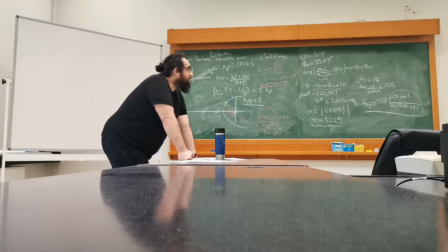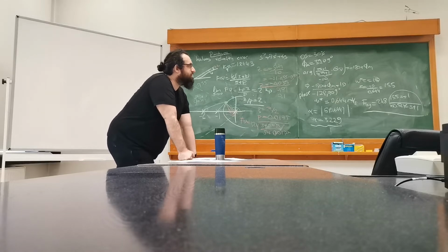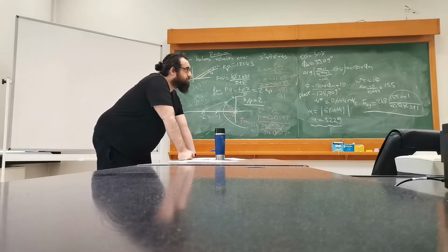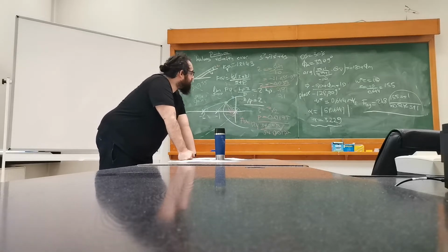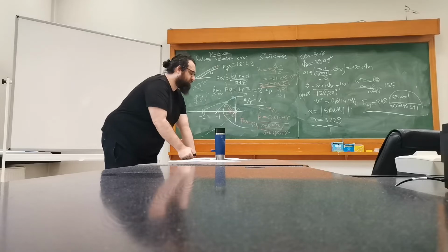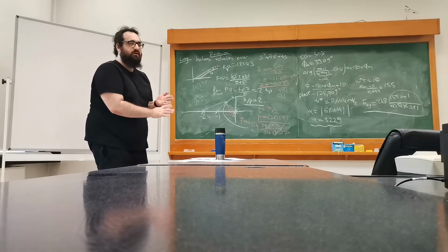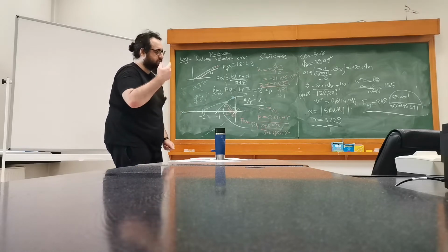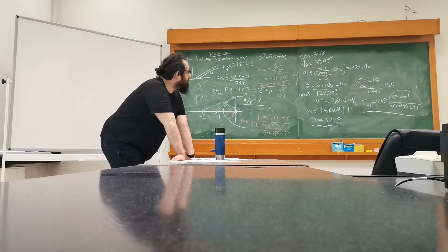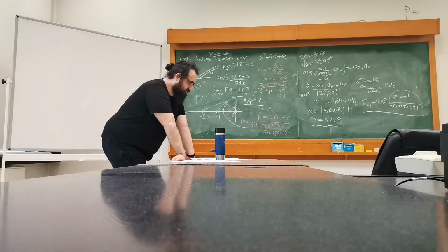So yeah. It seems like on the right we have a better way of choosing it, because we definitely find out what alpha should be, what tau should be. We just directly calculate that. But here on the left-hand side, if we have the time domain approach, we have to basically choose it based on the ratio. What you can do is use maybe tabulation or something like that to look up the velocity error, which one is the best. If it's the best, let's choose it. But since we're thinking in the classical exam manner, we just choose it based on the ratio here. So that's basically question 3.